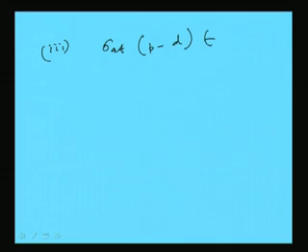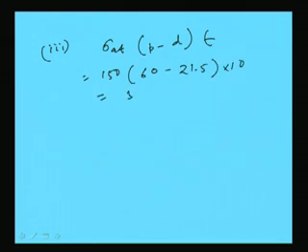And the strength of angle per pitch will become sigma AT into P minus D into T. That means this will become 150 into 60 minus 21.5 into 10. So, this will also become 57.75 kilonewton.